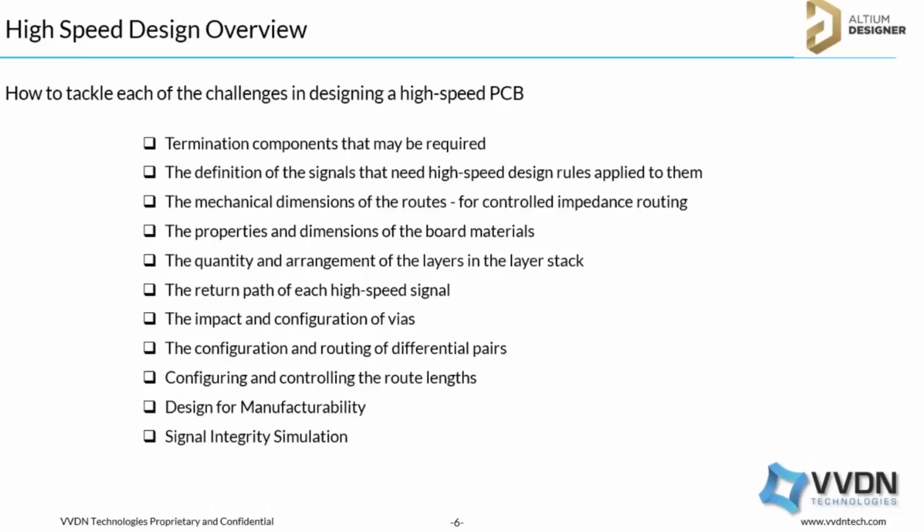Impedance comes in when you are handling a high-speed design, because the issues we have seen in the previous slide, like EMI, crosstalk, reflection, noise, everything is based on the track width, right? Routing impedance and the length matching.